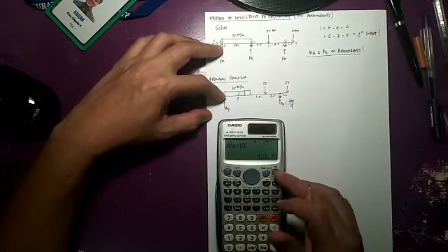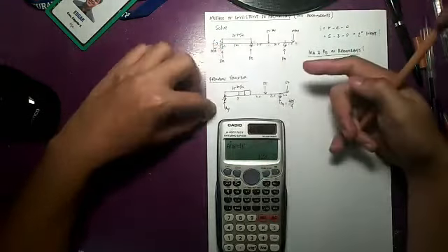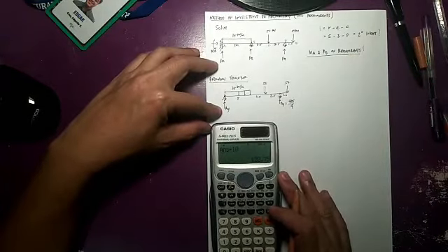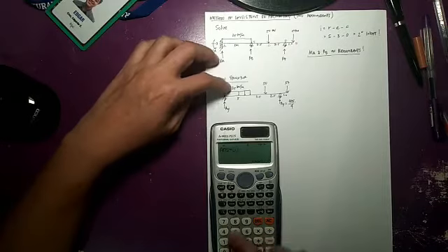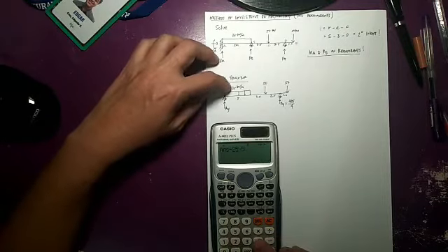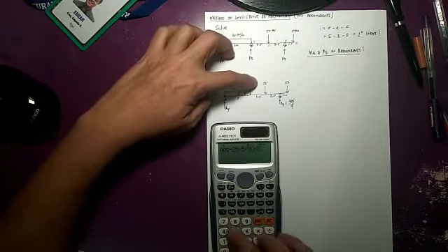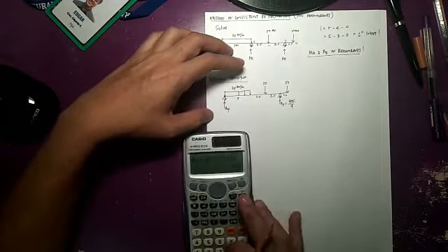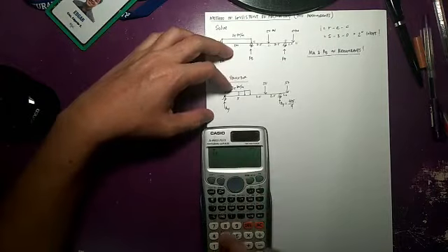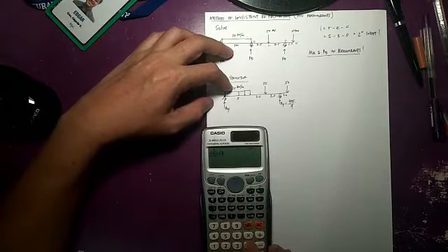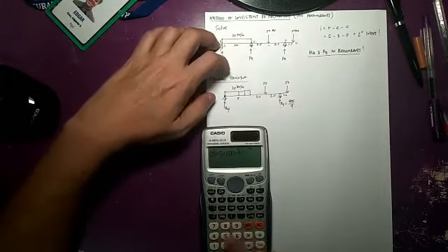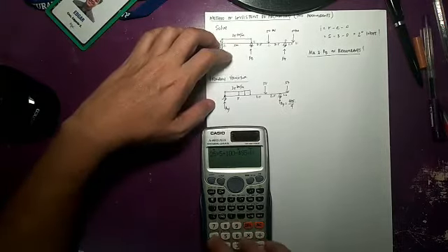If we sum up forces vertical, I could solve for AY, and that would be 25 times 5 plus 100 minus the reaction at D, 495 over 4.